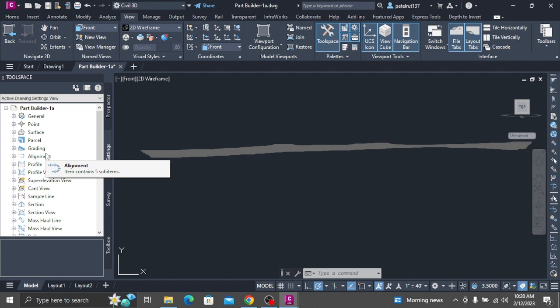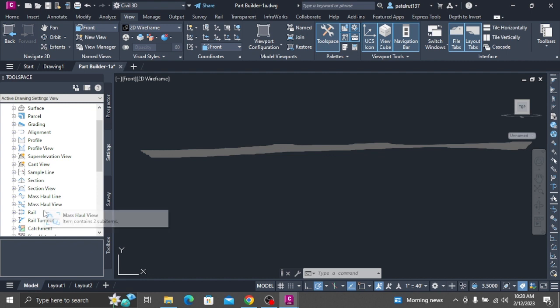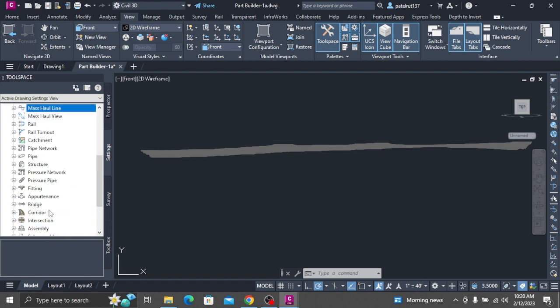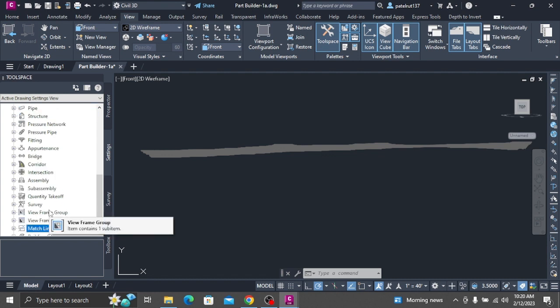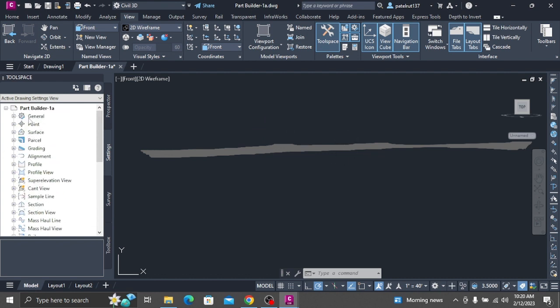Right-click Fixed Center Fixed. The point is now fixed. Constraints that include this point will not move the point. Right-click Rim Add Constraints Equal Distance. Click the point at the top left corner of the outer rectangle, then the fixed center point. For the second pair, click the point at the bottom right corner of the outer rectangle, and the fixed center point. Repeat this step for the bottom left and upper right corners of the outer rectangle. This constrains the outer rectangle so that it is centered about the fixed center.